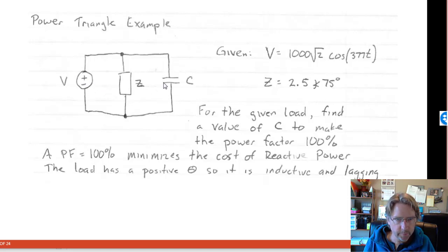So we add these capacitors. Inductive loads are more common in an industrial setting if you had a bunch of mills or robots or anything. If they've got motors, then they probably have inductors, and so most of the loads tend to be inductive. So this is a realistic example. All right, let's see our approach, and then you can take a stab at it.